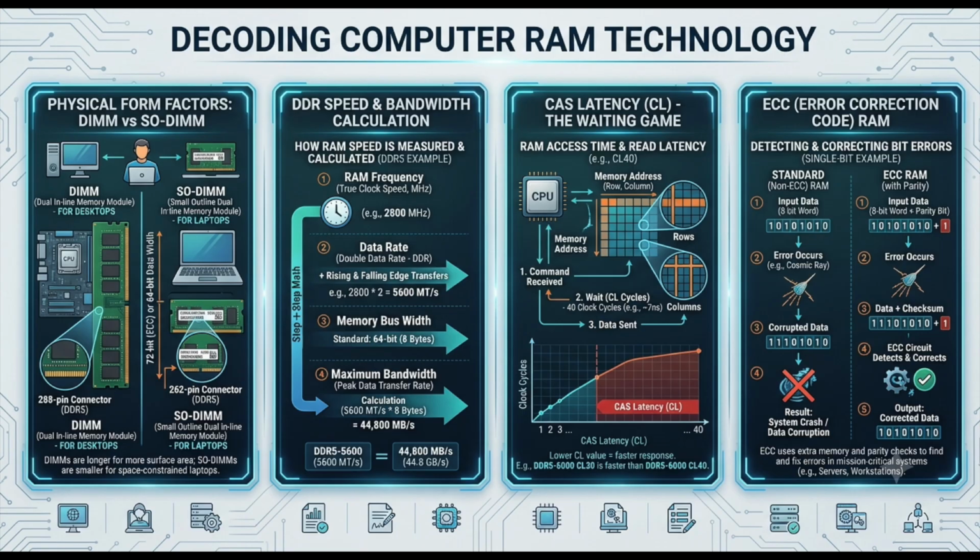Hamming codes. Instead of just adding one parity bit to an 8-bit byte, ECC memory takes our full 64-bit chunk of data and adds 8 additional bits, making a 72-bit block. Okay, so a bigger block. But it doesn't just do one giant parity calculation. It performs overlapping parity checks. Overlapping. So different parity bits are monitoring different intersecting groups of the actual data.